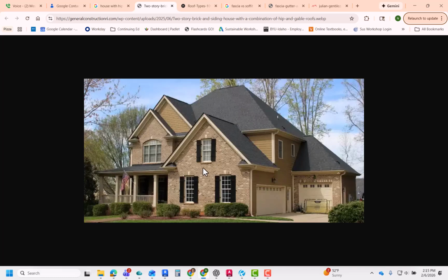Now let's explain what's really happening. In this case, you have your top of wall, which runs across here and then around the side, and then a roof going upward, and the wall has to somehow fill in a gap between the top of the wall and the ridge of the roof. So you always end up with this triangular shape. But again, this wall has to extend all the way up to meet the ridge or the top of the roof. Now over here, on the other hand, you can see the top of the wall, and it doesn't extend upward at all. Instead, the roof takes care of that job on all sides.